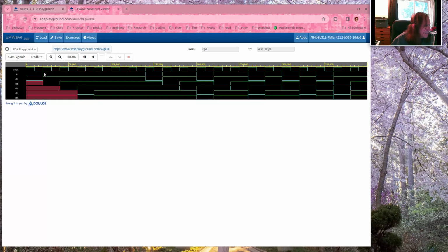But then on the next clock tick, our input was high, and that high value worked its way through. And you can see we had a big long high pulse like this. Well, there's a version of it delayed 1 step, delayed 2 steps. And this low value here on the input eventually goes through and becomes a low value here and here and here. So this is a shift register, right?